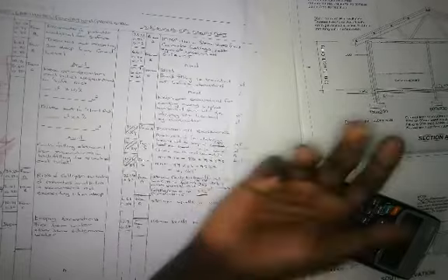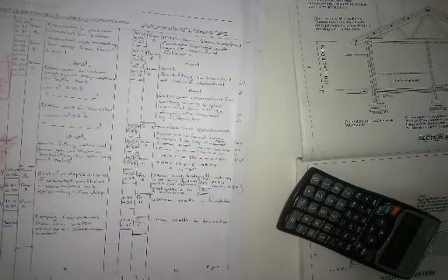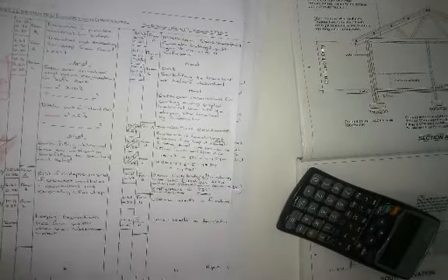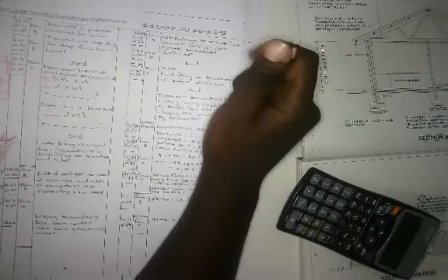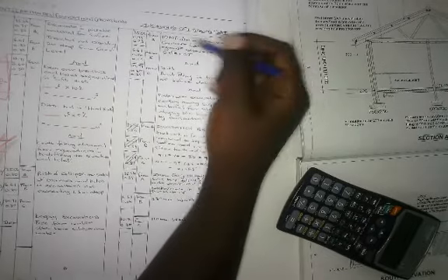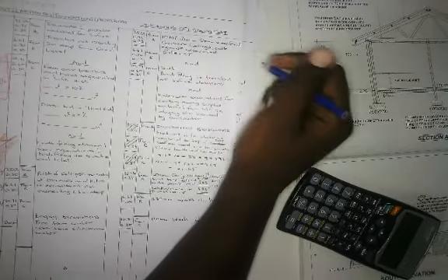The question that I got that was maybe a challenge to you guys was the adjustments. So for the sake of this, I'm not going to explain further the concrete because it's self-explanatory. You just take the center line, times it by the width and the thickness of your footing. So you're going to do the same thing for B and for C, because you've got it on your collects. On your collects it says 230 wall on 700 by 230 millimeter footing. So you just take that information and input it there, and then you know you're done.